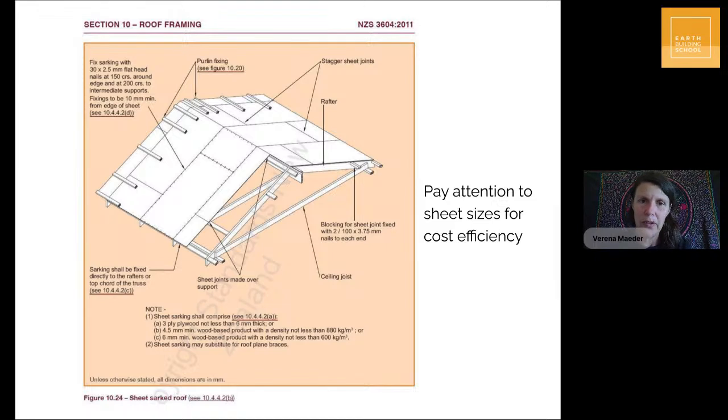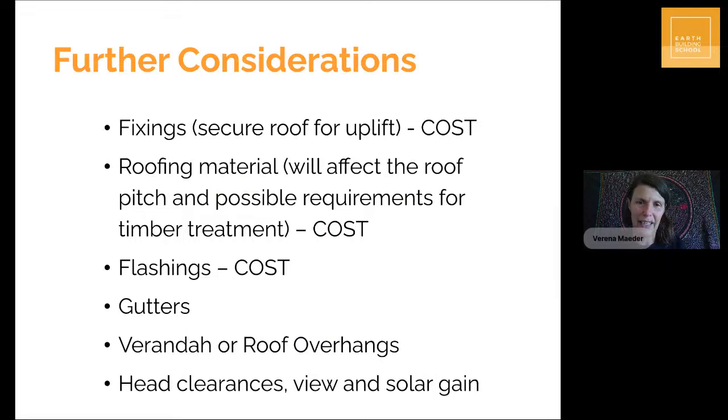It's a little bit of a nuisance if you design a building that is just a little bit bigger than, let's say, 4 sheets, because then you have to put in a strip and put in extra fixing for that and so forth. So really encouraging you to look down, look up, and think about material sizes, because on a plan, it's easy to just make a measurement up, but it would be so much easier to think about these sizes and allow for that in your plan, because it has a knock-on effect during building that can add labor and costs and so forth.